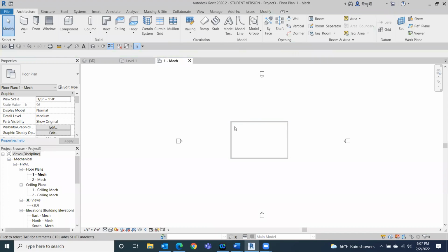So it was not allowing you to select anything under here. Correct. And then you went over here. Correct. Great. So if anyone is having the same issue, you should be able to select the walls like I'm doing here. If you are unable to, follow Jonathan's instructions and make sure this box is checked, select underlay elements, so you're able to do that.